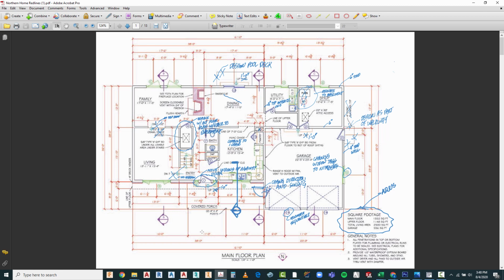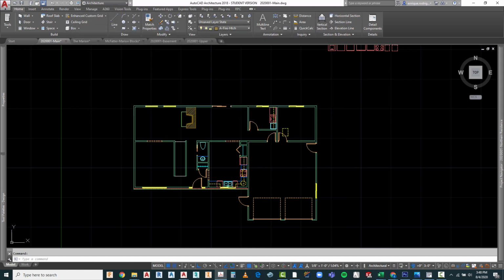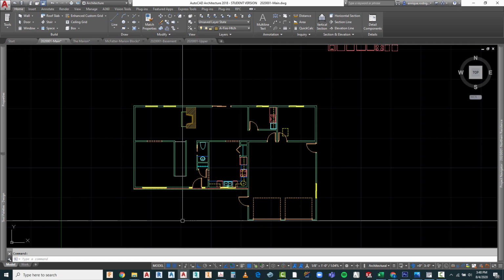That's basically going to be 22 feet over, and that's to the center of a 4-inch column. Because there's two 4x4 posts, we're going to add 2 inches to that. And so our dimension here is going to be 22 feet 2 inches. Let me go ahead and bring that back up so I can take a look at it as I'm drawing.